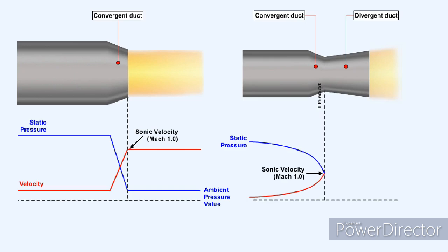When the gas enters the convergent section of the convergent-divergent nozzle, its velocity increases with a corresponding fall in static pressure. The gas velocity at this point now reaches Mach 1. As the gas flows into the divergent section, it progressively accelerates towards the open exit. The reaction to this increase in momentum is a pressure force acting on the inside wall of the nozzle. A component of this force, which acts parallel to the longitudinal axis of the nozzle, produces the further increase in thrust.